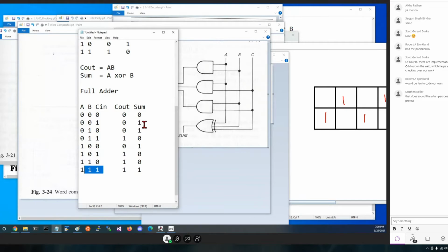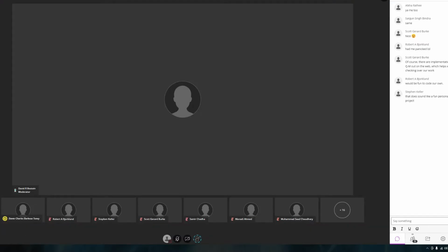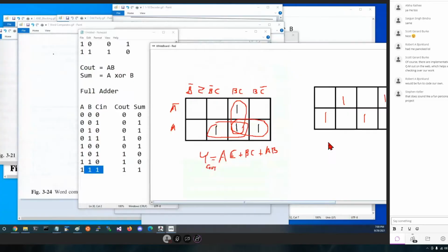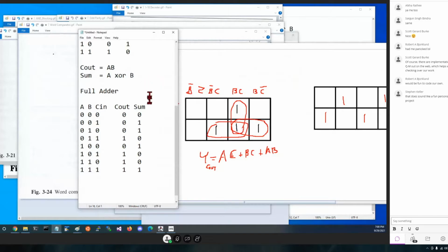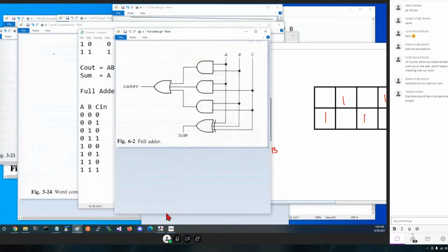We didn't learn this before, but now we know it. We can always come look this up again if somebody were to ask us that question sometime. So a 3-input XOR gate is exactly what that describes. Yes, it's not reducible in a sum of products way. You've got some horrible sum of products going on there. But it does do exactly what we need it to do. So we would have to build one of these for each column, and its carry goes to the carry in, which is the C, of the next stage to its left.